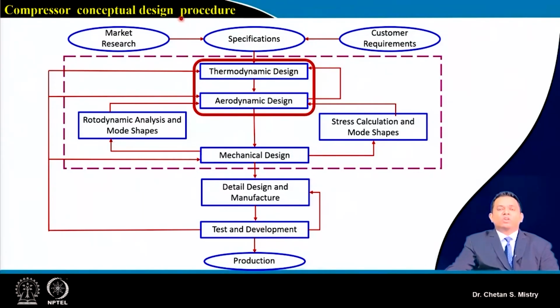So you can say this is the whole cycle, and this cycle is for a single compressor stage that we are discussing at this moment. If we consider that we have 10 stages, for all 10 stages you need to go iteratively through all these design aspects. And finally we come to the final design of the compressor. That is the reason this is very challenging, and it asks for a lot of understanding in terms of design, flow physics, and performance.